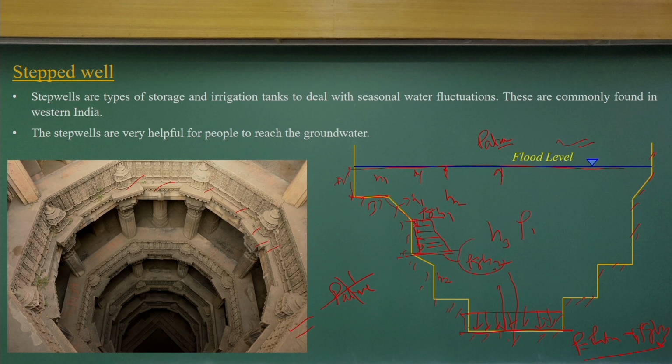So, we get the pressure diagram in trapezoidal form, and if I know this pressure diagram, I can compute the total force acting due to it. It is a very simplified way: find the area of the pressure diagram, multiplied with the perpendicular distance, often taken as unit distance. Then the area of these diagrams will tell me the force acting because of these pressures.